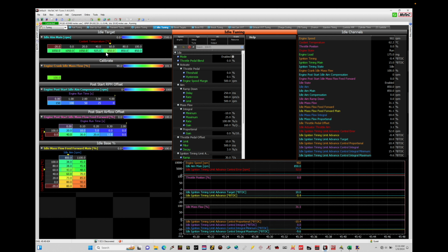So whether we're dealing with a 3-cylinder engine or a 12-cylinder engine, we'll call out our desired engine RPM here. Now, the RPM is going to essentially translate into a certain level of torque output from the engine to maintain that desired idle speed. So when we're talking about idle control, we are saying we want the engine to run at a certain engine speed, but what we're indirectly calling for is the control of the engine's torque output.